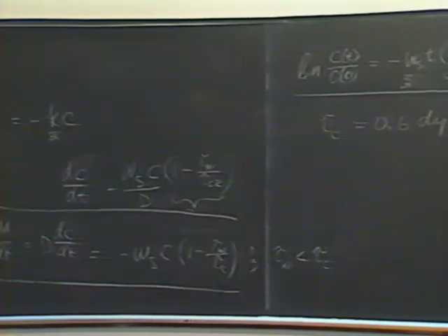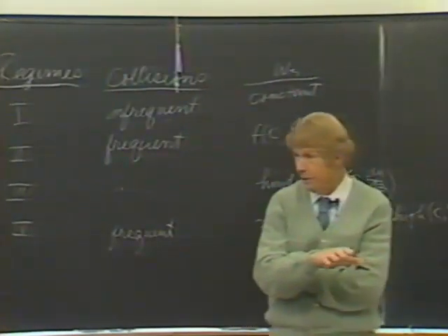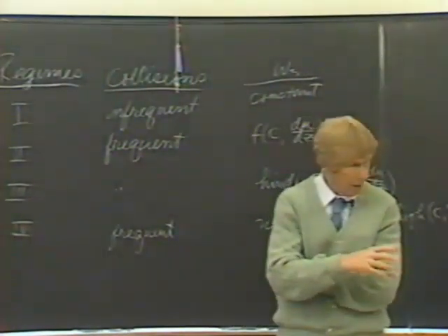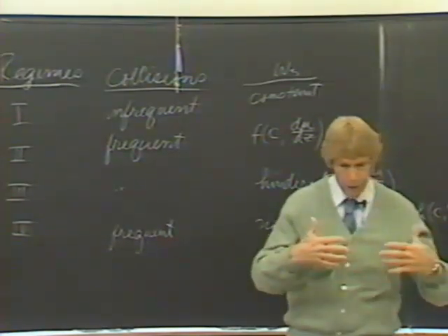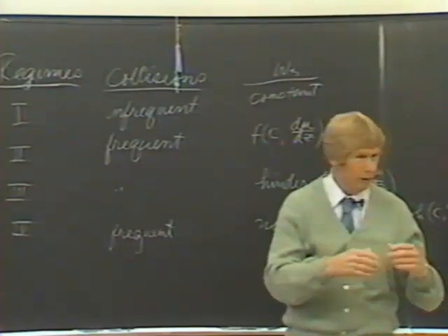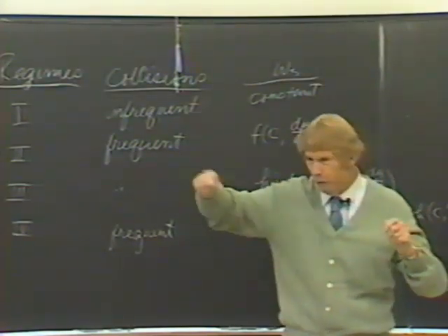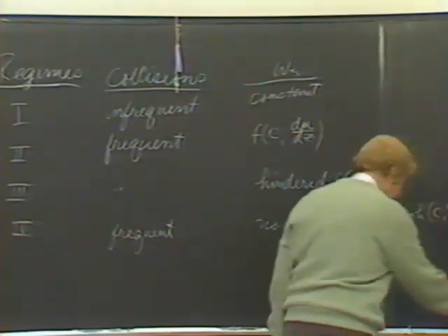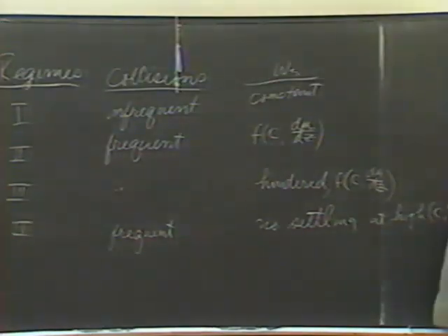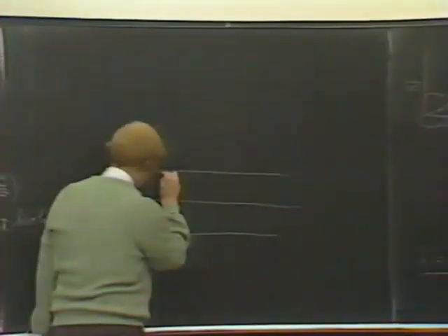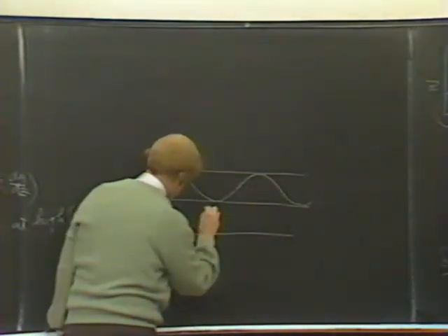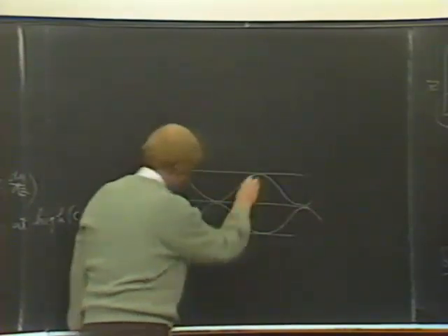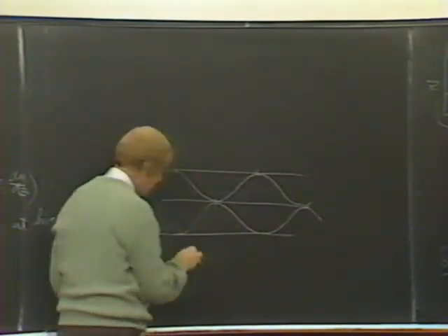But now we have W sub S varying in that region. Recall that I pointed out last hour that empirically we found that W sub S in this regime 2 is equal to some constant times the concentration to the 4/3 power after aggregation had been allowed to take place. That is, remember, with a plunger or by dipping a cylinder into a flume and letting the particles settle and measuring the median settling velocity. There were some that settled faster and some that settled slower, but the median seemed to fit this quite well.